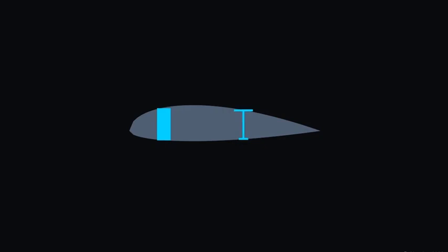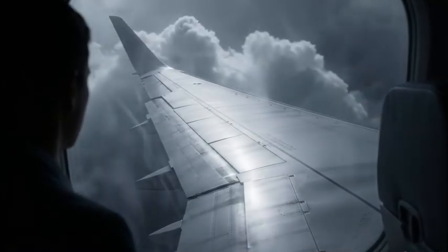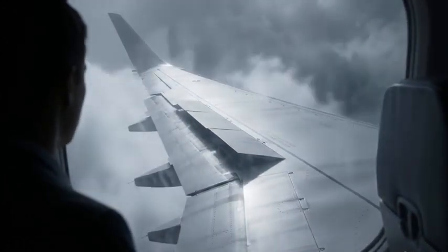This exact mathematical principle is deployed continuously in massive structures. This hand-drawn sketch of an aircraft wing illustrates the concept in semi-monocoque construction, outlining the internal webs and flanges. Inside a wing, the internal ribs and spars function as complex, unsymmetrical channels. They have to perfectly absorb and manage extreme aerodynamic shear loads without violently twisting the wing out of the sky.